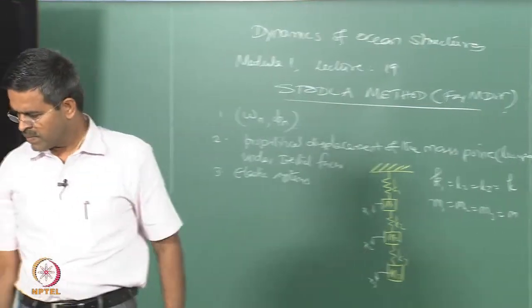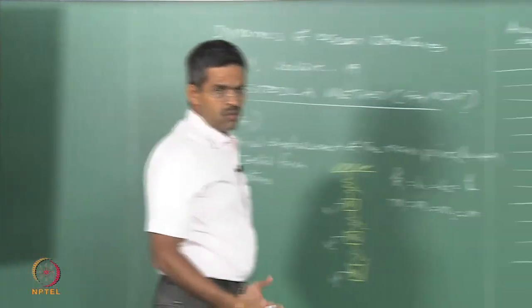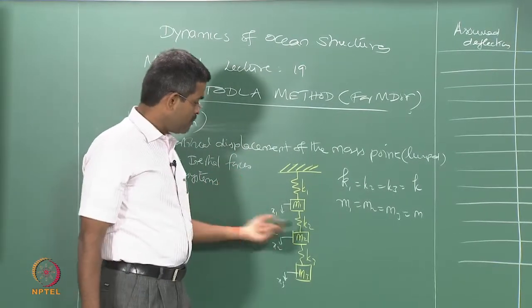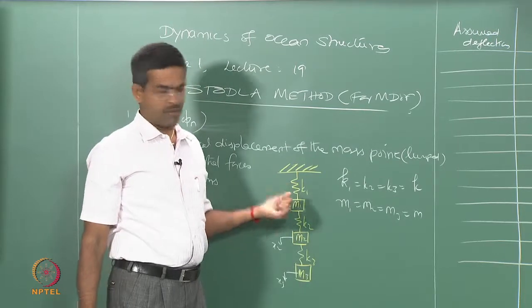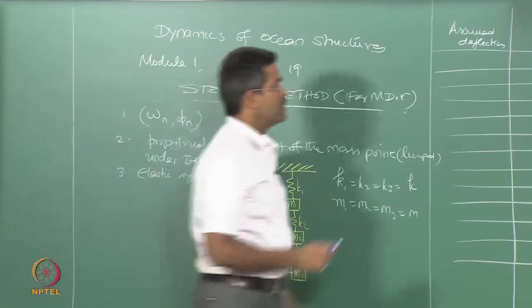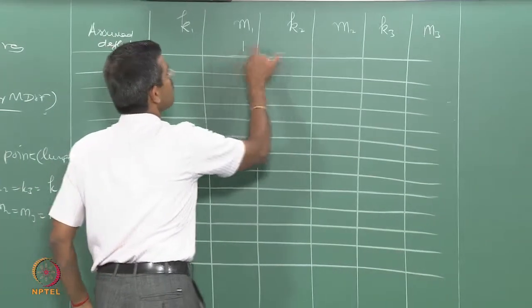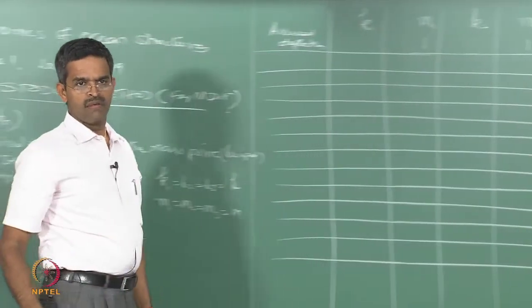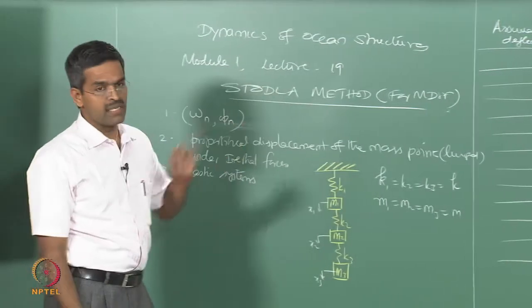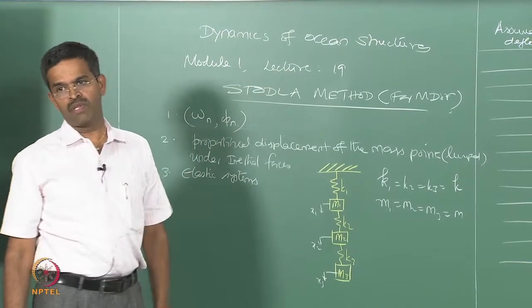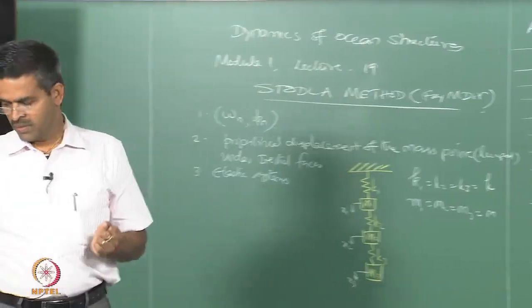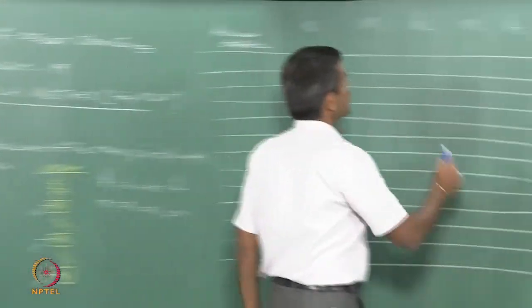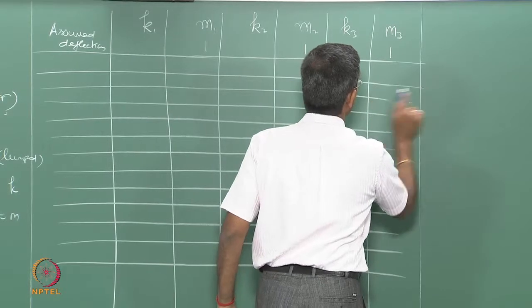Okay. So since we do not know the proportion of the mass, that is what is the proportion of M2 and M3 versus M1, I mean which is heavier, we have no clue. Let us assume that all of them are going to be displaced by the same proportion, which may not be correct, but the one catch here is all of them are positive. It means I am looking for the fundamental frequency. Okay, I am not allowing the change of sign or a zero crossing in the mode shape.